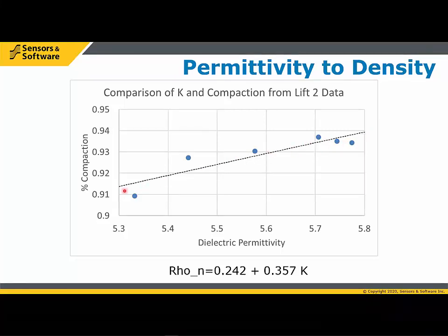A number of variations on a theme here, but the idea is you come up with this relationship, density related to the permittivity, and this is your function G in the last slide, and that's the one that has to be done on site. And that's why some of the people are now talking about using the permittivity instead of doing this conversion, because this conversion has turned out to be difficult to do in a reliable fashion. So I'm not sure if that answers all the questions.